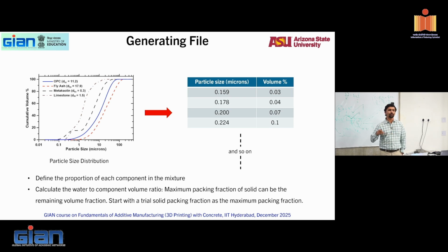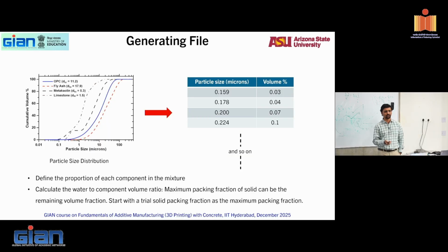Now you can't have a maximum saying, let's say you have 40% is water, then you can't go to a solid volume fraction of 70. That 40% you need for water also. Again, there are air voids that form when you mix. If you want to account for that, you will have to put 40 plus the air voids percent and select the rest as a solid fraction.